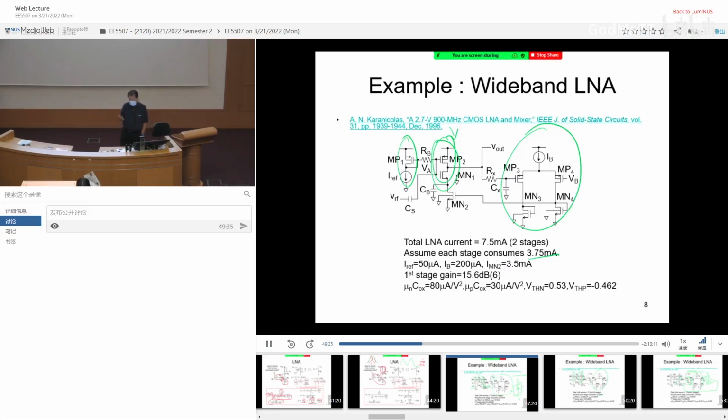Here it is arbitrary, depending on how you want to assign, but I like nice numbers. So of the 3.75 milliampere, right away I think, let's give 3.5 to the main amplifier. Then I am left with 0.25. I have 2 helping circuits. The first branch is so simple, give it 50 microamps. And the second branch, a bit more complicated, give it 200 microamps.